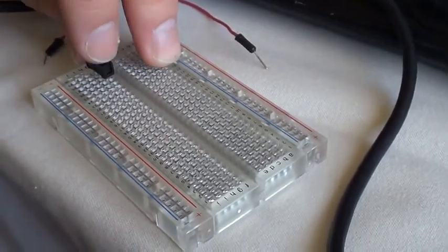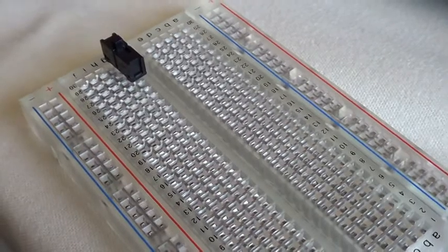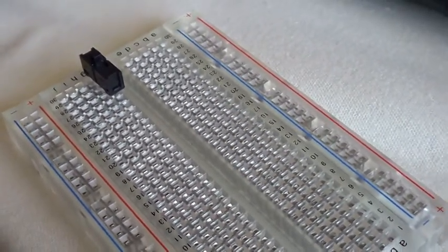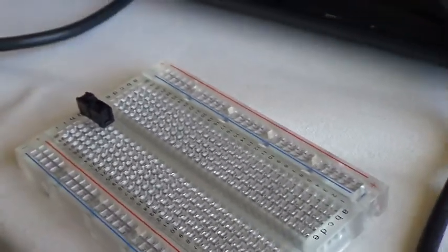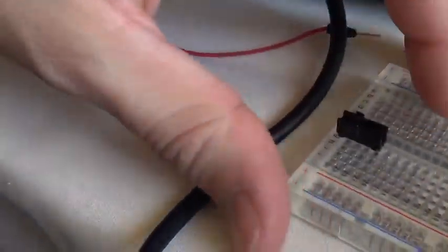Alright, so let's go ahead and hook one of these up. You're going to want to pick a port, one of the digital pins, and choose that as the input pin for the switch, and then we're going to connect another side to ground because we need some reference point for the switch to be either high or low.